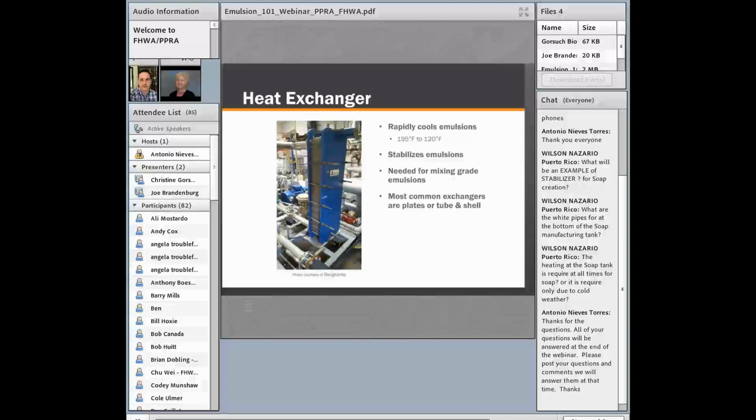When you have a mixing grade emulsion with too much heat in it, that means you have too much energy. So when that mixing grade emulsion is mixed with stone, the reaction happens faster, meaning your emulsion could break on the stone too quickly and clog up pug mills.